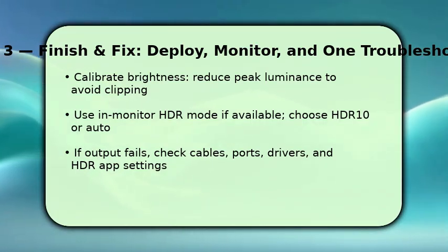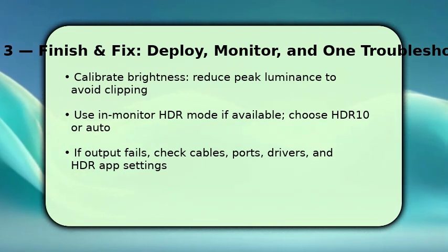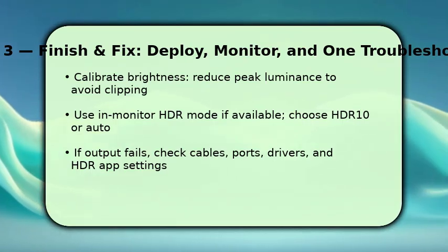If you still see no HDR, restart the system, reseat the cable, try a different port, and confirm the app supports HDR. One key troubleshooting tip: swap to a known good HDMI 2.0/DP 1.4 cable.